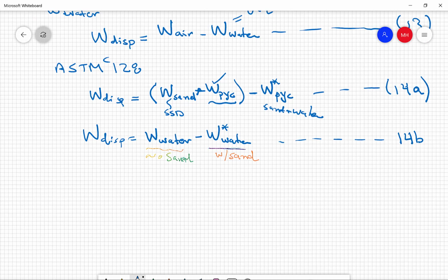So this displacement method cannot be used successfully using the oven dry aggregate, because the absorption will take place during the measurement. Since the bulk specific gravity will be different in the oven dry case, we write the bulk specific gravity always with a designation where we carry the calculation.